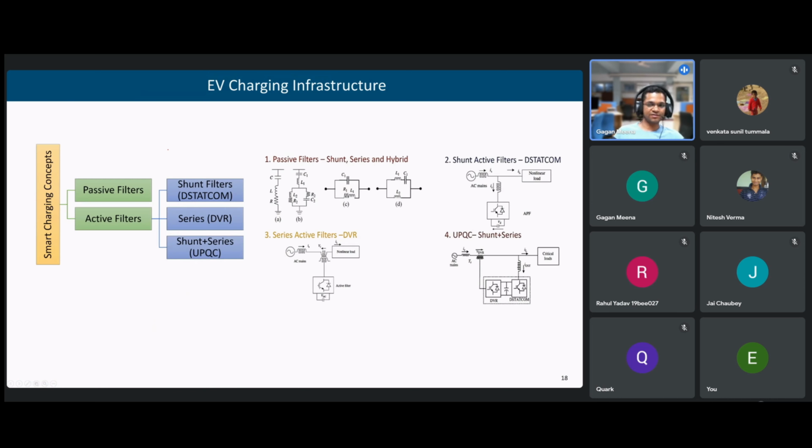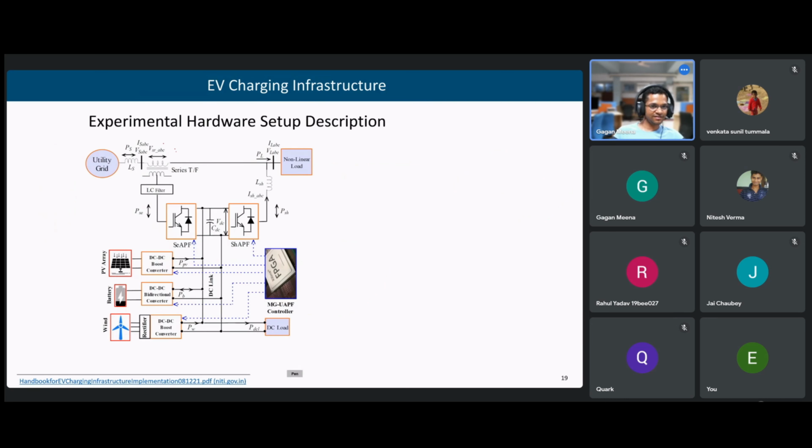Based upon this, you can see how this is arranged, how this is connected. Because this is connected in series with this line. This is series. Here, this is connected in shunt. It is not in series with this line. So now can you tell which type of compensation this is? Grid side converter or load side? Is this series or shunt?